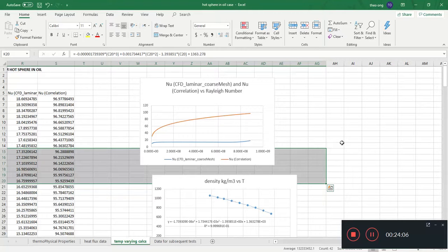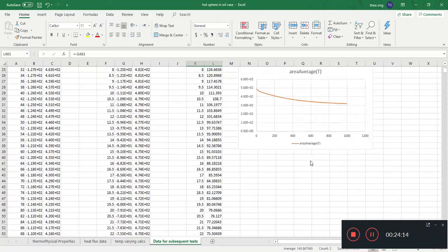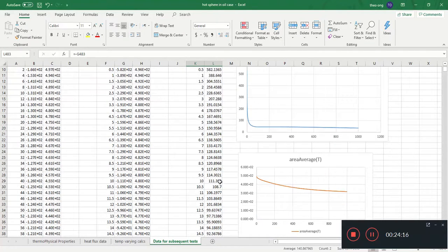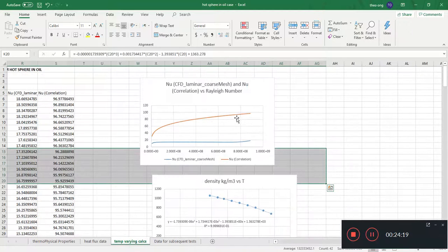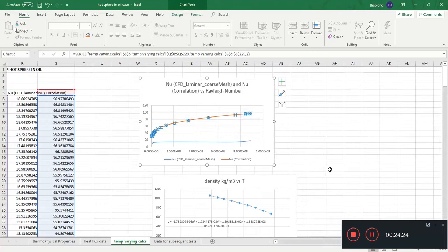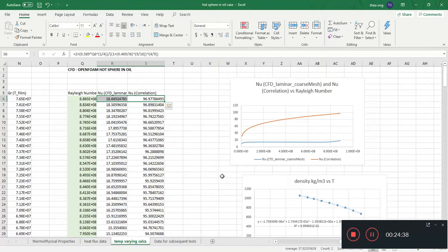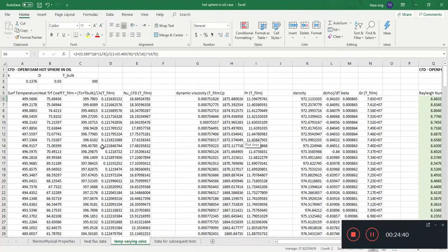So while in the beginning we have a nicer heat transfer coefficient, which might match this Rayleigh number much better, because this Rayleigh number has a Nusselt number about 5 times that of the coarse mesh. So the heat transfer coefficient should be about 5 times higher than, let's say, this.